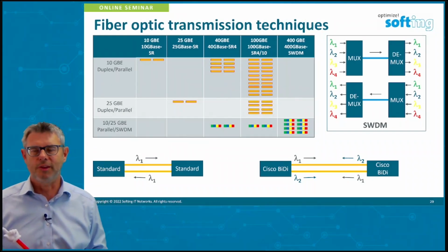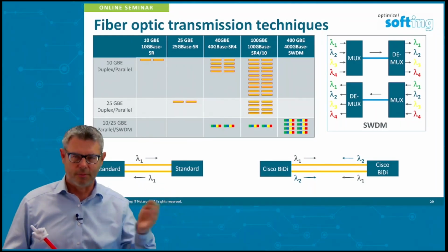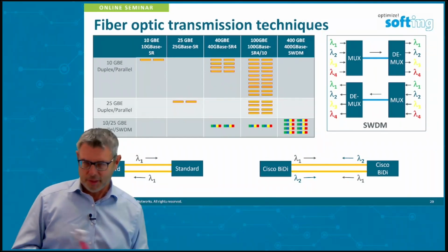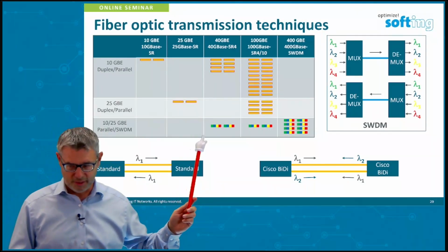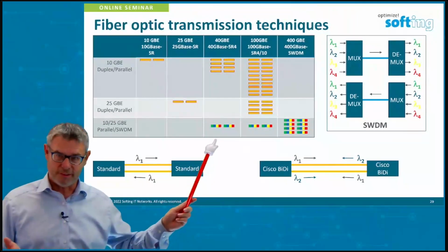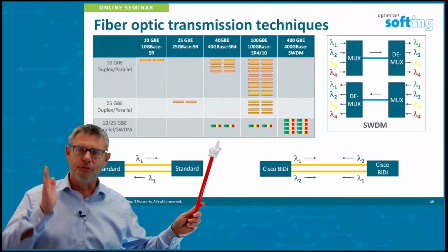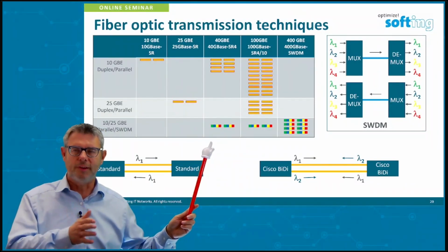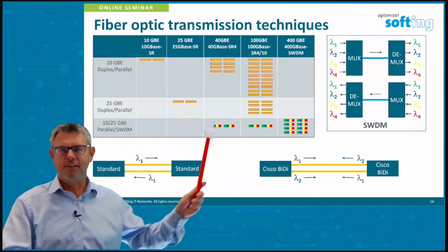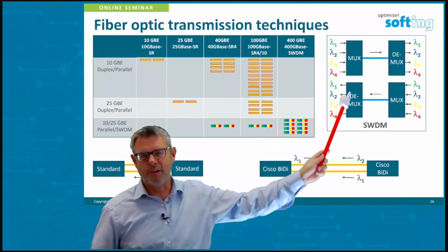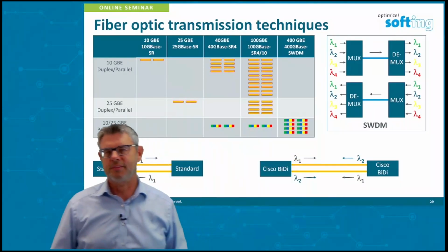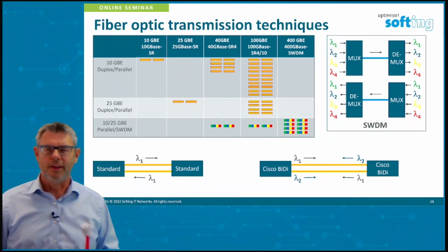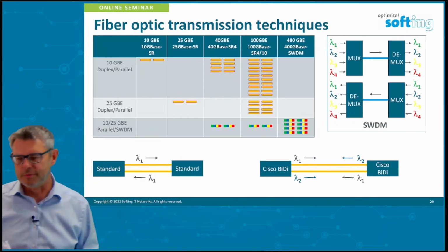Usually we have one wavelength, 850 nanometers or 1300 nanometers, and this is the working wavelength, the carrier frequency, let's say. But in this case here, we are using a short wavelength dense multiplexing system. So we're having here 4 carriers, 4 different wavelengths. So the signal is split up in 4 wavelengths and transmitted, let's say, these colors in parallel over one cable. And this multiplex signal is demultiplexed on the other side. And on one pair of cable, you can transmit 40 gigabits.